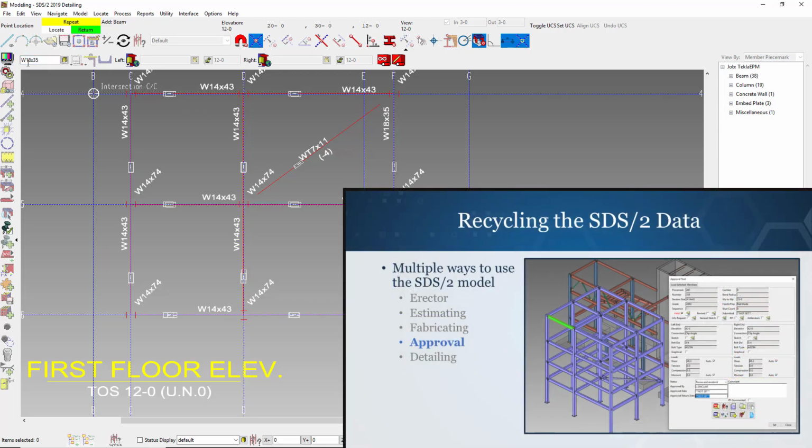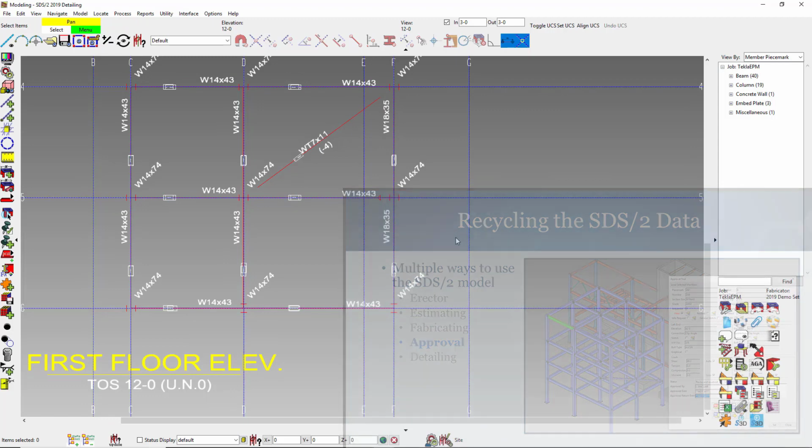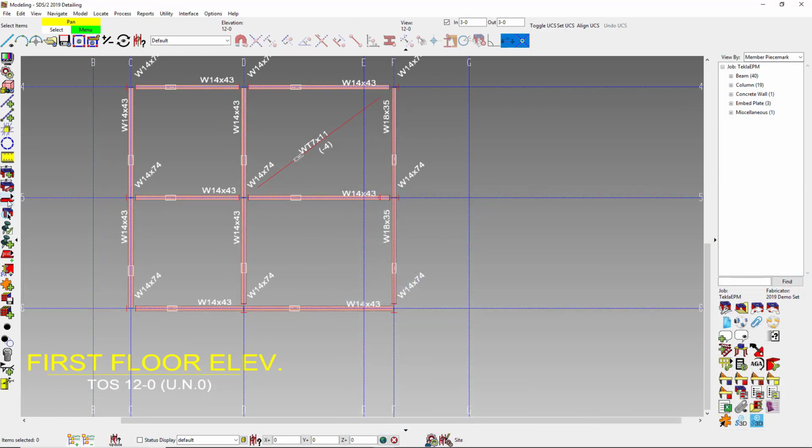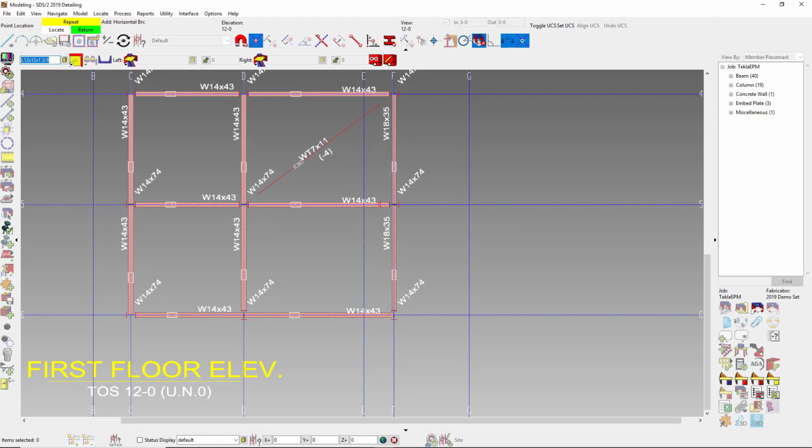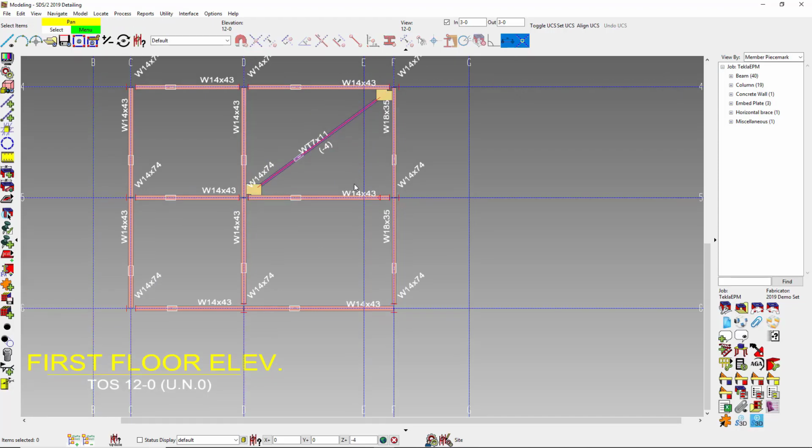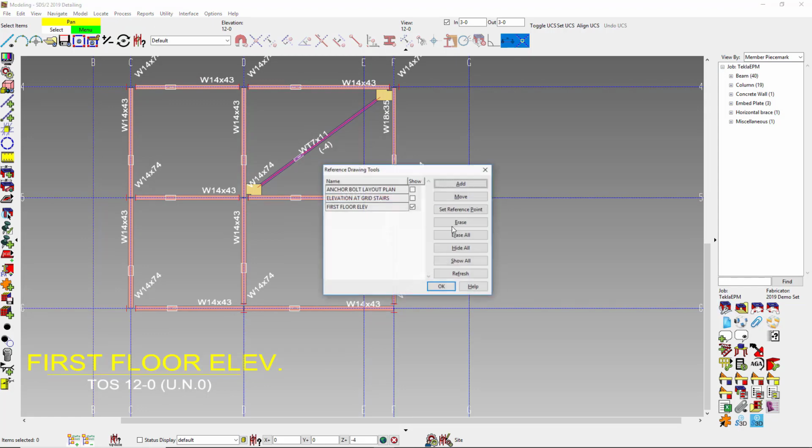And now approval. So let's say I don't do any of the detailing, but I'm just the checker. The approver can then use this tool, or there's a lot of other tools in there, select that piece of steel, set it to a status of maybe held, the reason maybe why it's held, or I can set it even to the approved date that I want this to be. Then I can assign different colors in the model, and it's very powerful to see. I can also send those statuses out to, let's say, Tekla EPM.